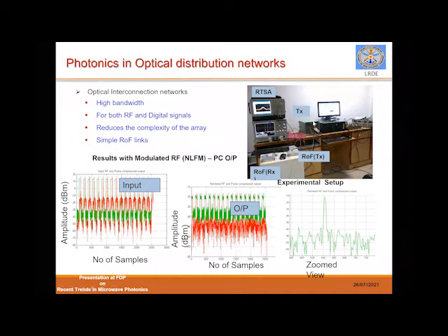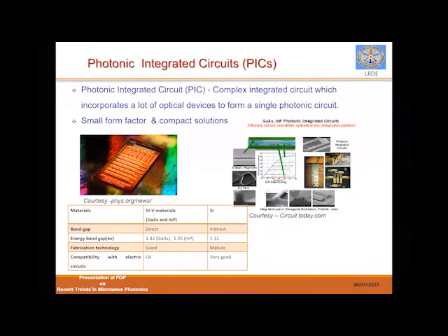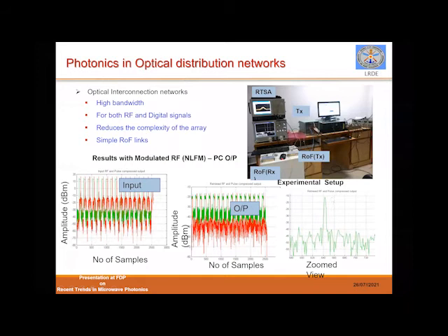You can see that even after passing through the fiber link, there was no degradation in the performance of the link, and I could retrieve back the original signal. And this is the zoomed version of this pulse compression output. Even here the main criterion is what the first side lobe level is, and you can see that it is pretty low here, so not a problem at all.